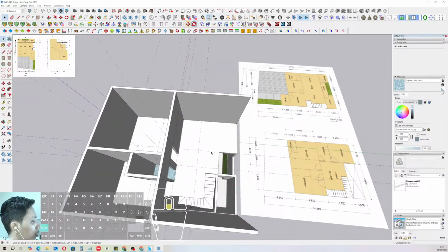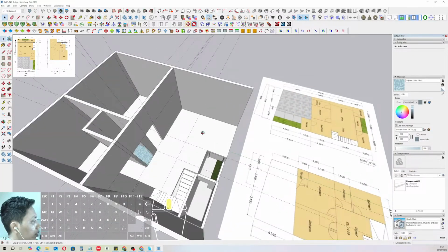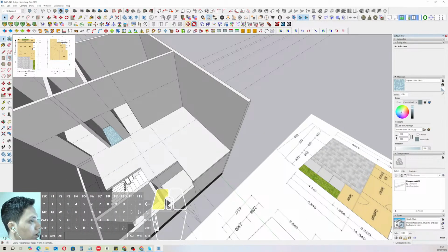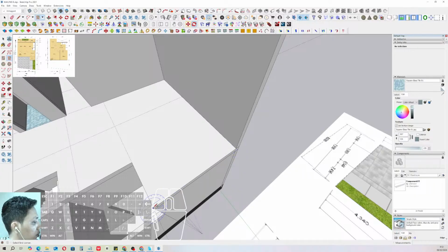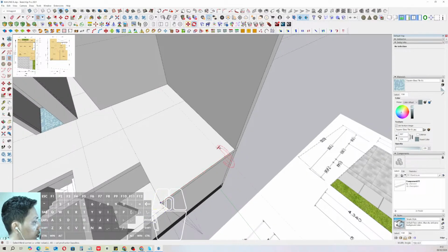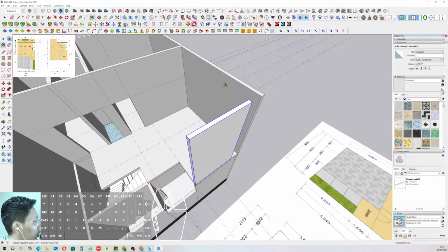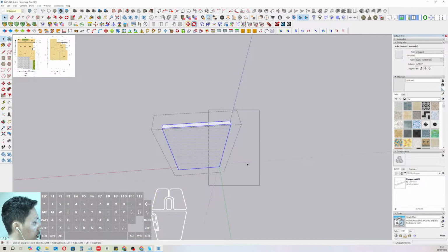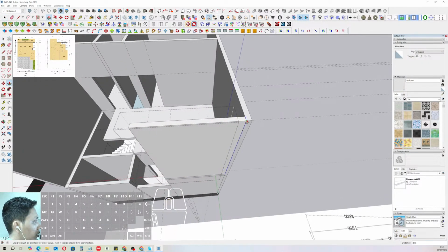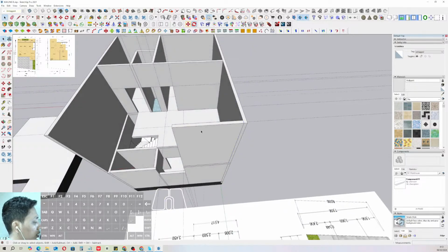And then okay, we can make another wall in here. We can select the rotated rectangle and click from this corner, for any position first, then we can type 150 millimeter. Then we can click and extrude up, and also click this wall plane and make sure that it's connected well on the existing wall over there.